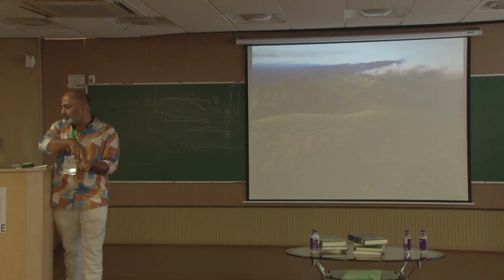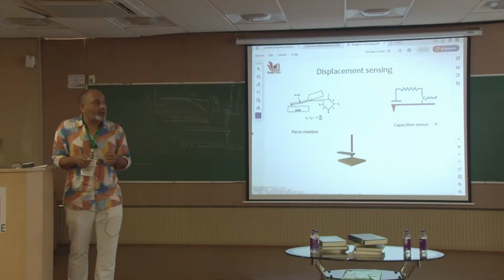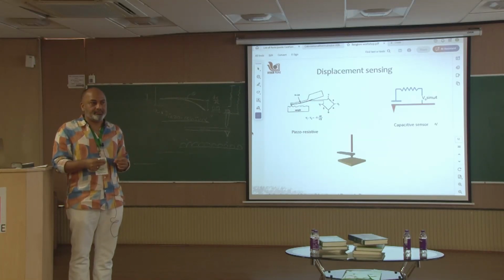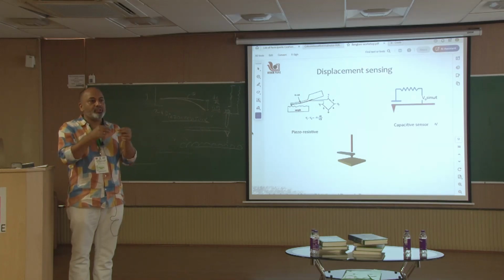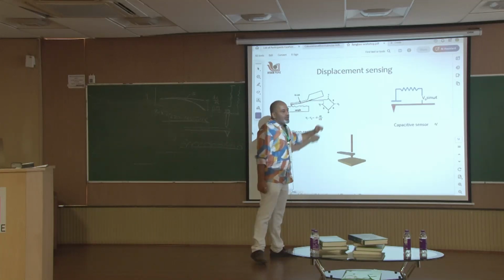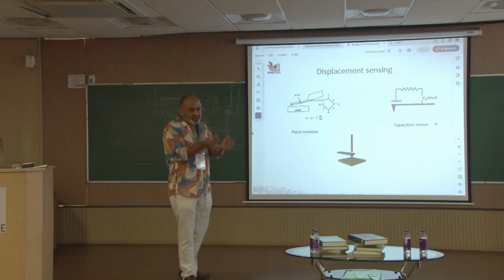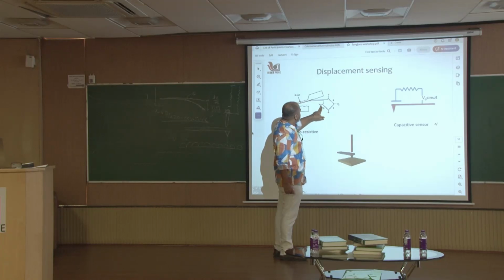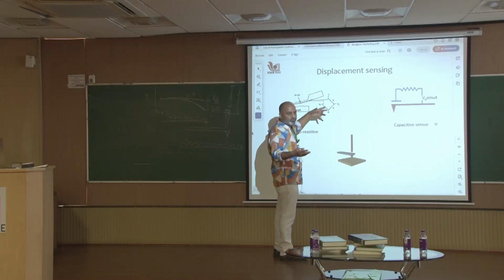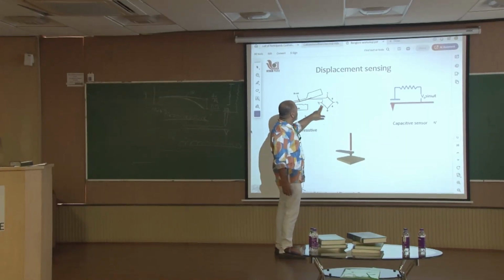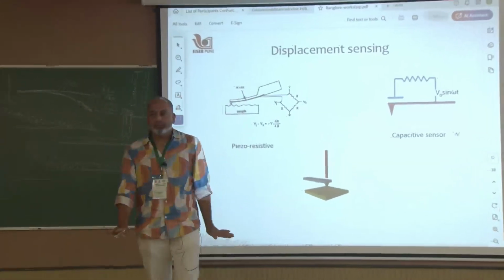So the idea is to have a gauge element which, under strain, will suddenly change its resistance. Suppose you put that into something called a Wheatstone bridge, again 12th standard physics. A Wheatstone bridge is four resistors, and if you apply some voltage and ground this, then there is a V1 and V2. If you balance this properly, there is an equation, Kirchhoff's equation. If you balance them properly, no voltage drop. You apply this voltage and you can balance so that V1 and V2 are the same.